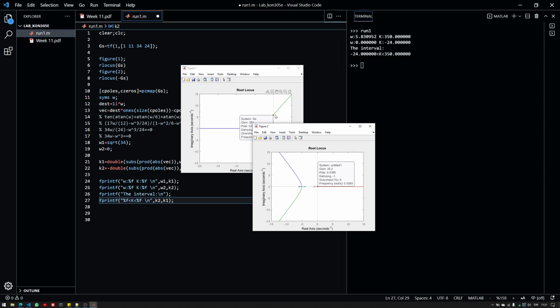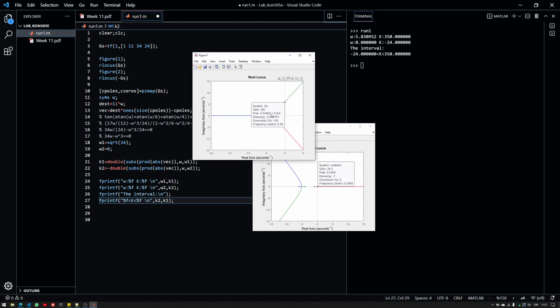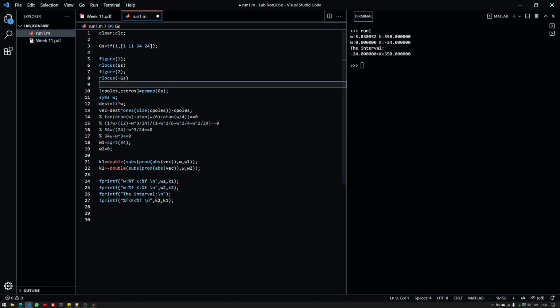So if you want to increase the accuracy of your root locus plot in terms of the gain values, you might go ahead and provide your own vector to this, so it'll generate the root locus with high precision in that interval. So let's give it an interval of 0, 0.01 up to, let's say, 360, which is hopefully sufficient.